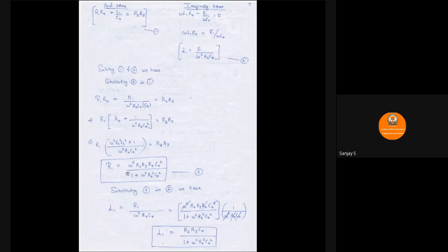At the same time, the expression for R1 also does not contain L1 inside. So both the unknowns are found. This is how you generally solve any simultaneous equation. Two variables, two equations. So equation 3 gives the unknown resistance, and this expression for L1 gives us the unknown inductance.